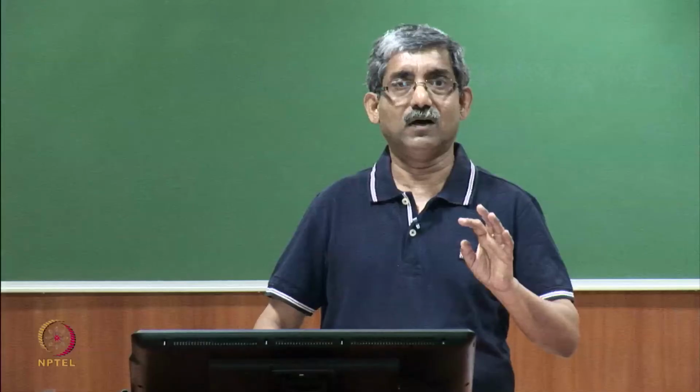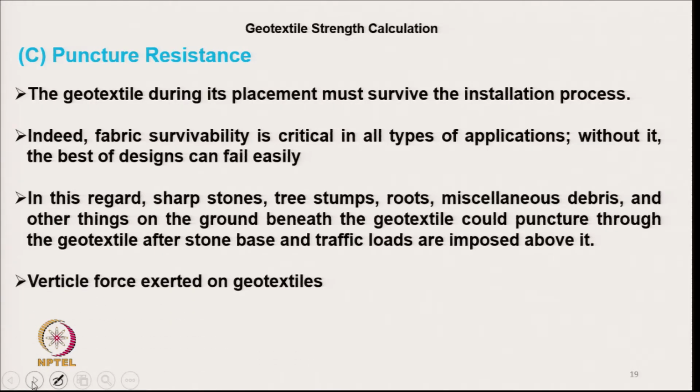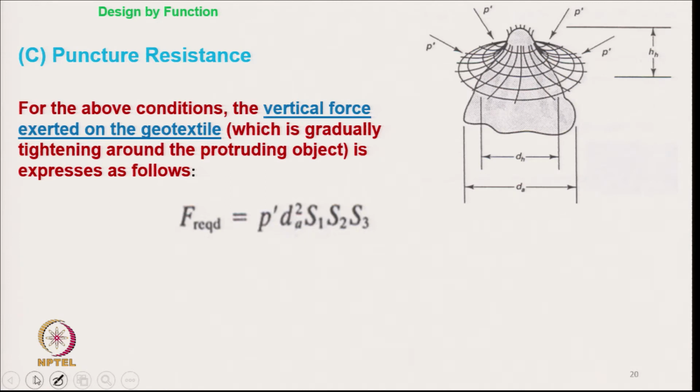So, these objects may create puncture in the geotextile, where the vertical forces are exerted by these objects on the geotextiles which may create puncture. So, we must know the puncture resistance of geotextile for all these survivability characteristics. So, this survivability function is very important.